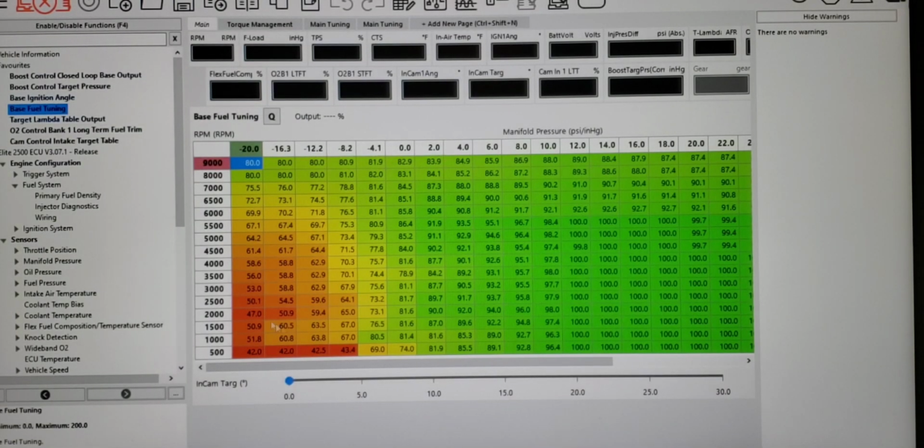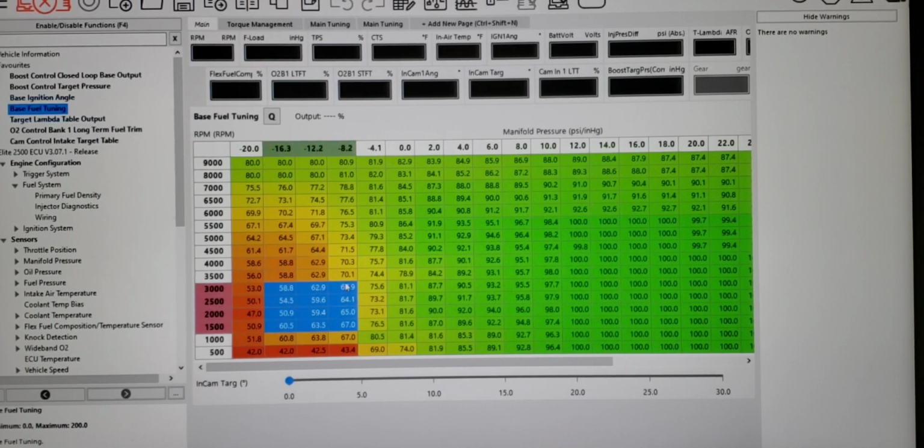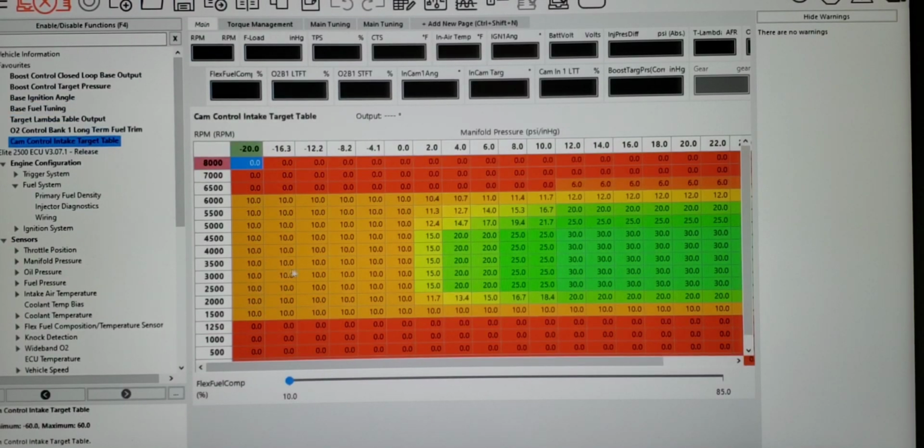You can see that it's applied some trims, and this is an area that it doesn't really cruise because of how we did the cam timing map, but you can see that it did start to populate up. I should probably interpolate these numbers realistically, but it cruises here at 10 or 15. We can look at 10. So the numbers that we're seeing there don't really matter because it's not using that.